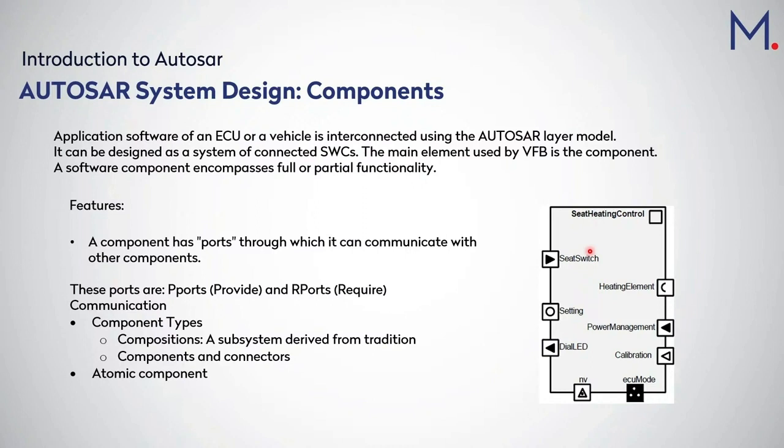And there are different port interfaces. There are three types of port interfaces in Autosar. Client and server ports: services required or provided by software components. Sender receiver ports: data is exchanged between sender and receivers via these interfaces. And there are calibration ports, so that static calibration data can be queried using calibration.